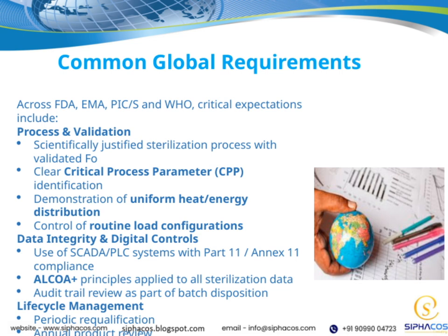complete, consistent, and enduring. An audit trail review becomes an essential part of batch disposition, allowing us to verify all process steps and data are properly documented and reviewed. Now, let's discuss lifecycle management. This involves periodic requalification of sterilization processes and equipment to confirm ongoing performance. Conducting annual product reviews and trending CPP performance helps us spot any deviations early and maintain process control over time.